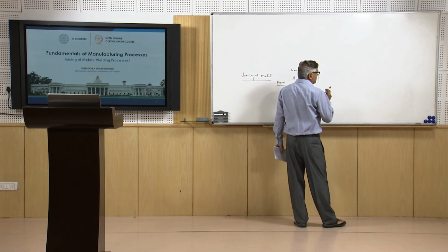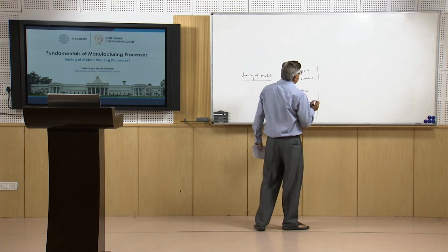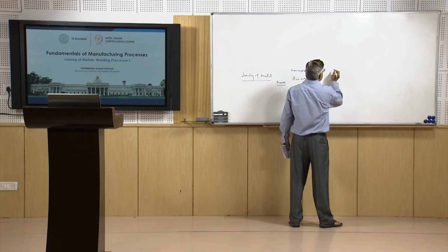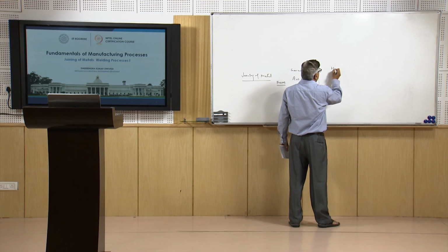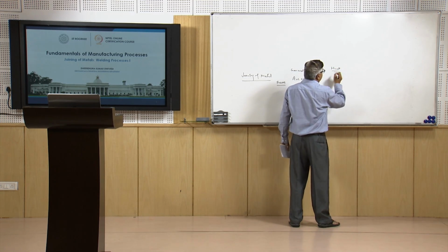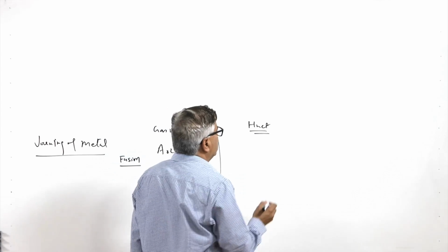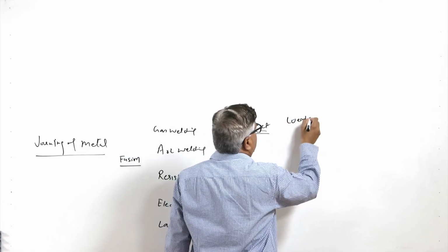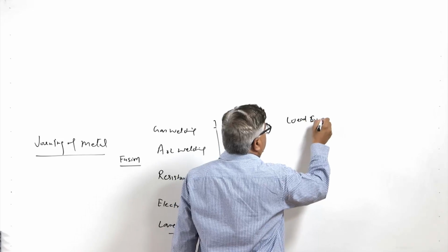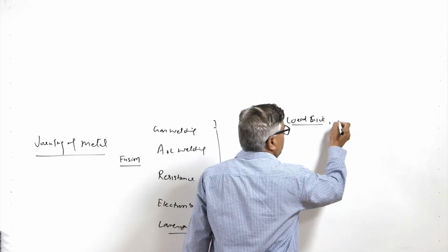Apart from the heat aspect, the gas welded joints you will see. So, let us talk a little bit in detail about how the heat input affects the joint. We know that the weld size increases with the increase in heat input.